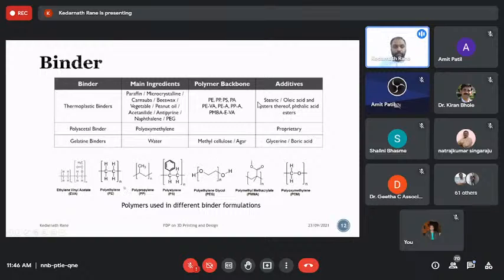When it comes to the chemical composition or the chemical structure of some of the binders, they are listed. I'm not going into details how they look like and how they are facilitating the process, but it is worth mentioning that complicated polymeric chains are not advisable for binder formulation, because they take effort to remove during the debinding and thermal debinding process.